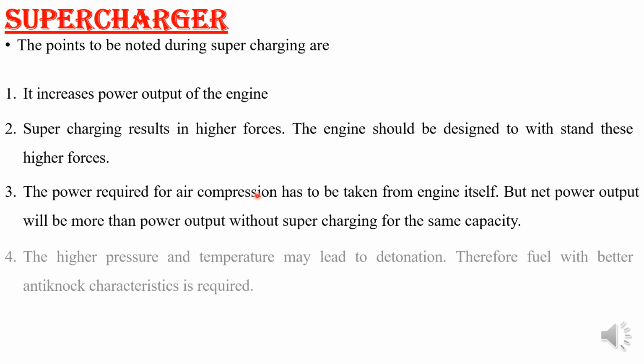Then the fourth point is that high pressure and temperature may lead to detonation. So with supercharging, how much you have to boost has to be decided properly, because the higher the boost pressure, it may lead to detonation or knocking, and engine life can be reduced. So we have to take care of detonation as well as knocking of the engine with respect to your boost pressure.